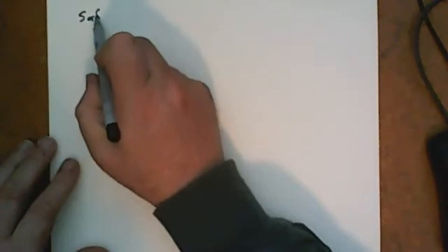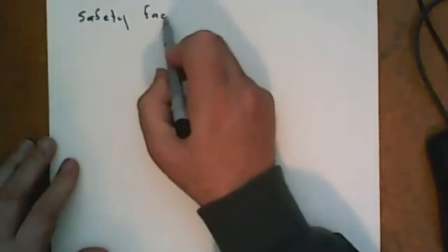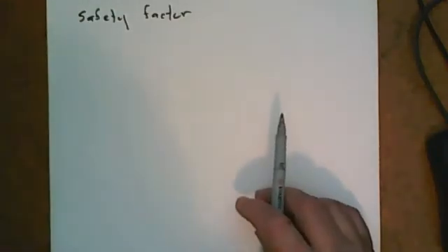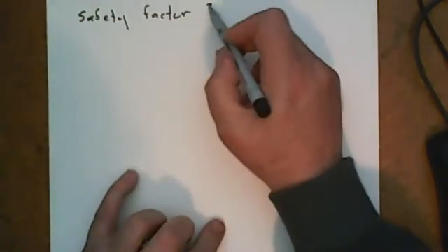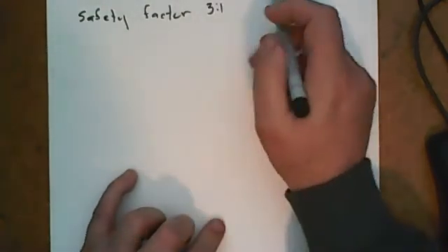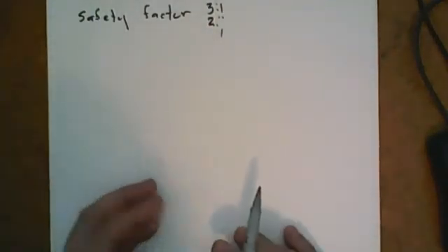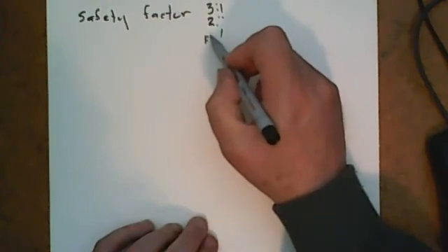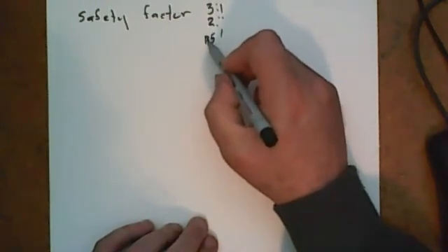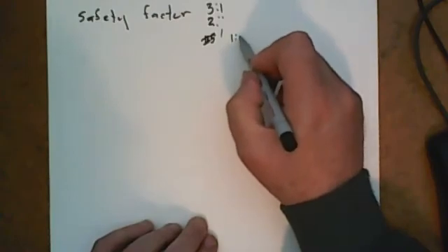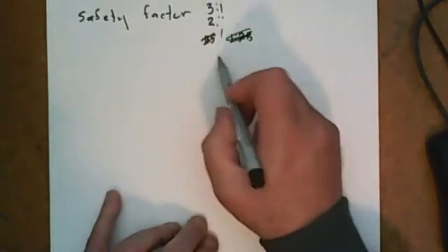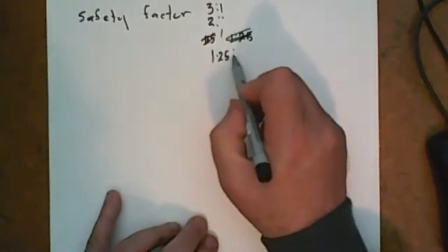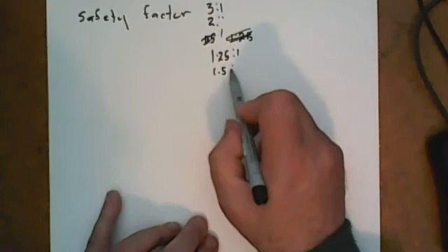We will try and ignore this and pretend this. And the normal way that we get around uncertainties is something called a safety factor. So when you build stuff, you know, like a car or something, you might design a 3-to-1 in the suspension system, or you might design a bridge with a 2-to-1, which means it's twice as strong as it needs to be. If you're setting up an uncrewed rocket, it's 1.25 to 1. If you're setting up a crewed rocket, it's 1.5 to 1.